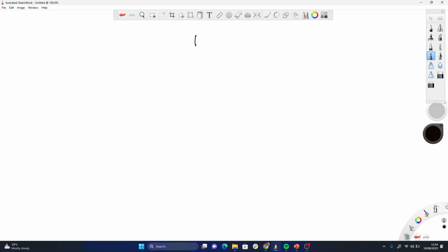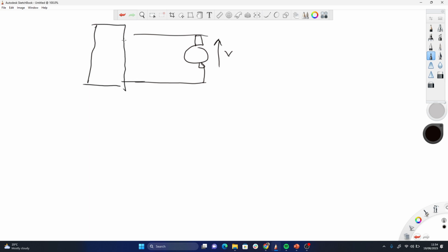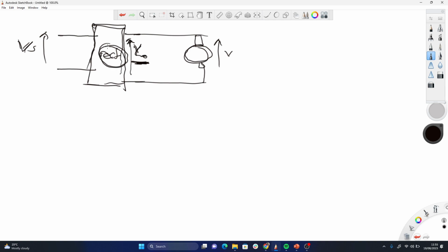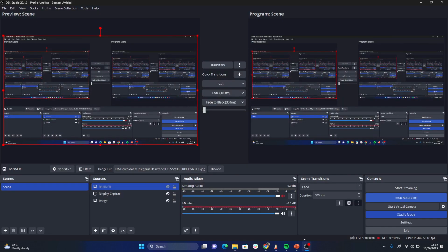Because I'm just saying that if you have a motor like this, and I want to vary the voltage of this armature here, I connect a rectifier here, right? Because you know that with rectifiers, you can vary the output voltage by varying the firing angle. So if I have an AC supply Vs, you go through the rectifier. The rectifier gives me a certain output DC voltage. Then that DC voltage output becomes the input to the motor here. So as I'm able to vary the firing angle of this rectifier, I can vary the output voltage. And once I can vary the output voltage, I should be able to vary the speed of the motor.